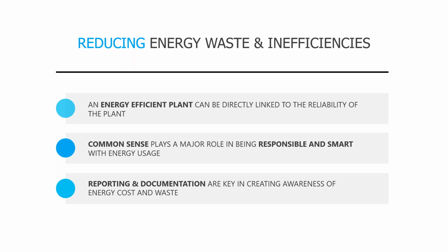Walk with the purpose of looking for ways that we can do things more efficiently, mainly with compressed air. Sometimes we go into these plants and we see people using compressed air for things that just don't make sense, like cooling a motor or cooling a fan, sweeping the floor, moving parts. Think about ways that we can do that same task, but do it more efficiently using another method.